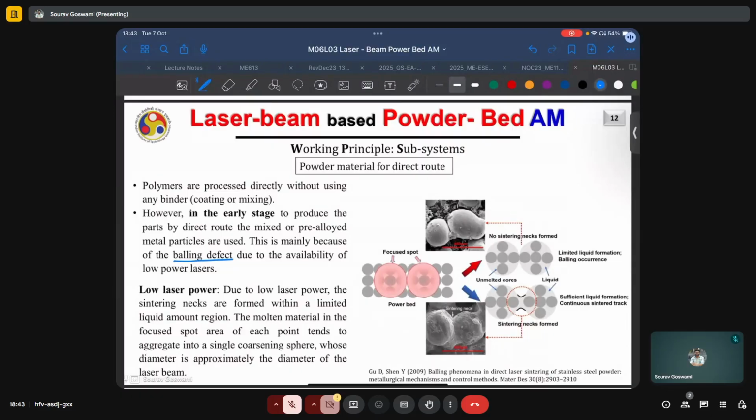Because at the outset, the reason that selective laser melting took, say, a couple of decades to emerge from the selective laser sintering process is because laser technology had not kept up. Originally, we had CO2 lasers, which are typically of a higher wavelength, like 10 micrometers, and also are not very powerful.